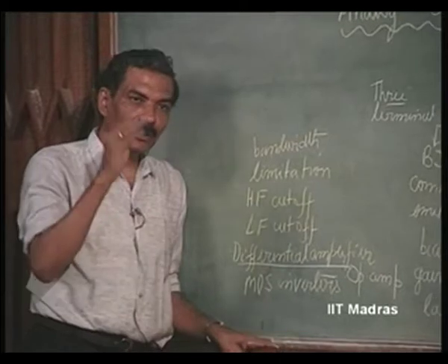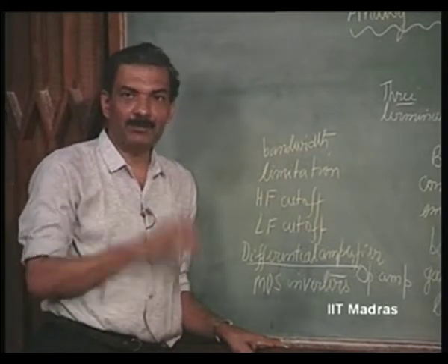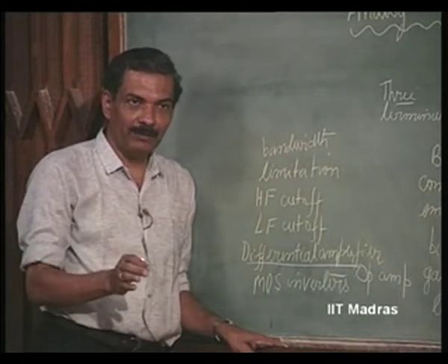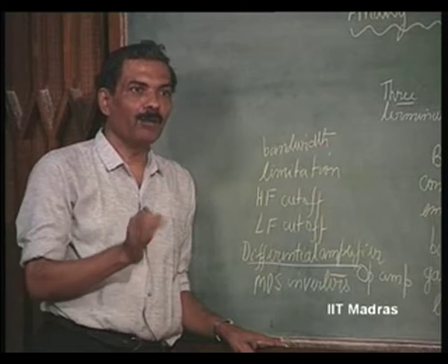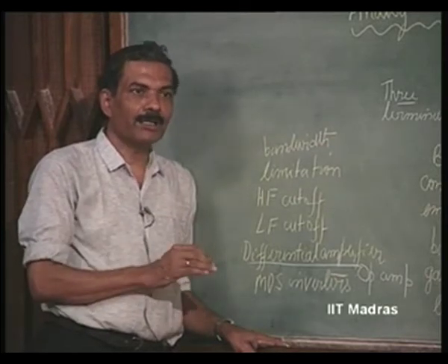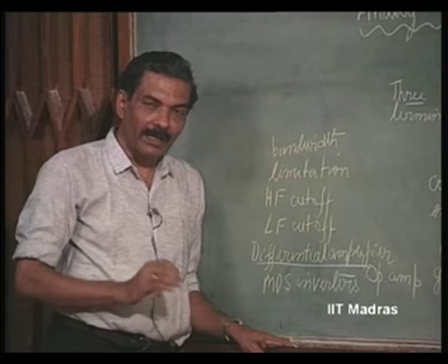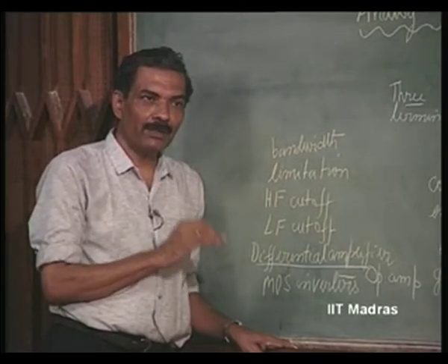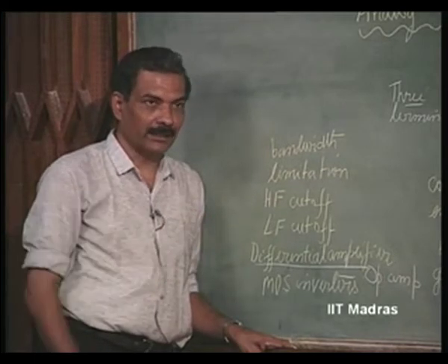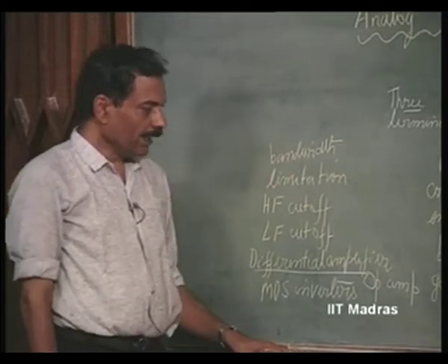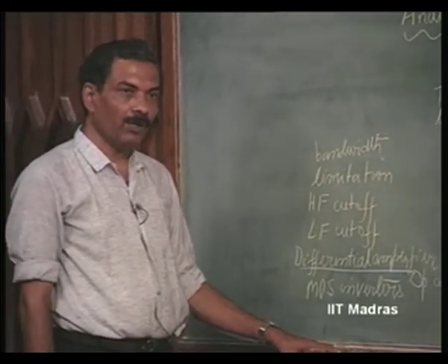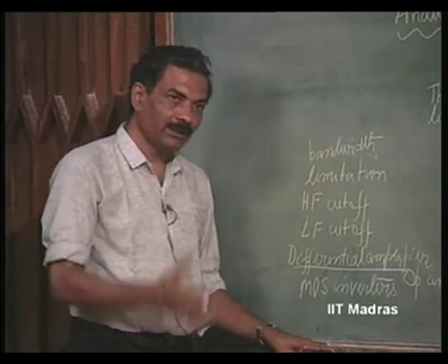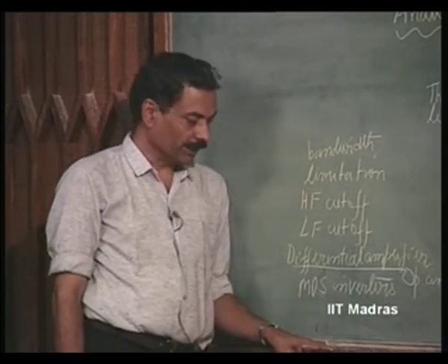Therefore, we get 4 types of op amps corresponding to the 4 types of sources or amplifiers which we have discussed, which are called operational voltage amplifier, operational current amplifier, operational transconductance amplifier, and operational transresistance amplifier, wherein always the concentration is over improving the forward transfer parameter by cascading. So we had concentrated on the design of the operational voltage amplifier, and we saw how we can give an equivalent circuit for the op amp, the operational voltage amplifier.